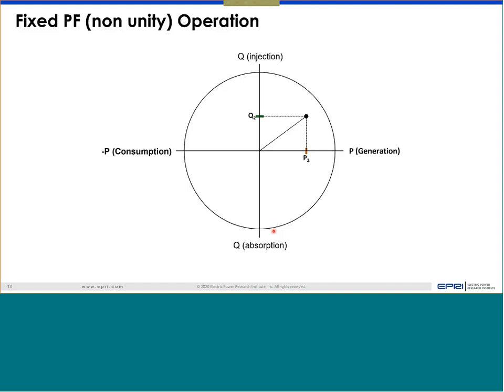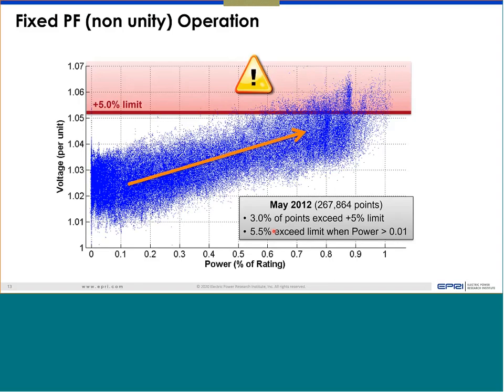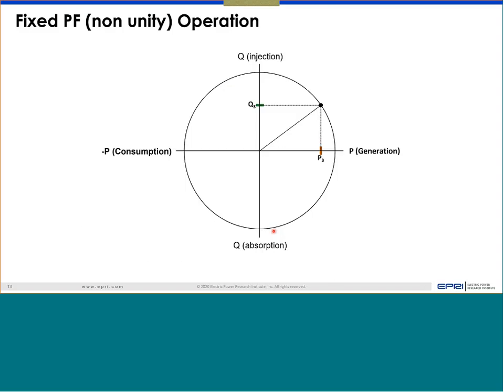Once it gets to a situation where maintaining the power and Q will push the operating point outside the circle, at that time it will limit either P or Q. So if the power has gone here, and the corresponding Q point would be here, it will never go there because it cannot operate outside the circle. In that case, either it will limit the Q and stop here, or it will limit the power and go to a Q value of something like this. That will depend on the reactive power priority or real power priority.